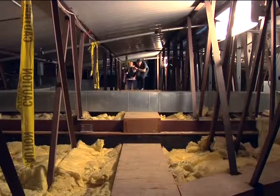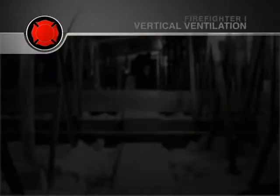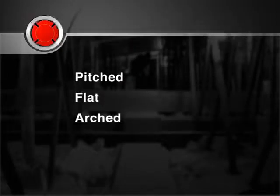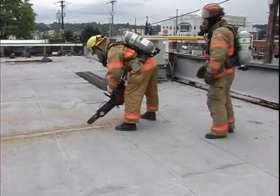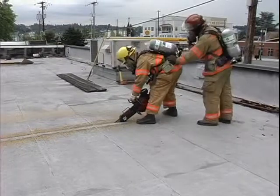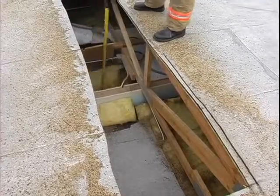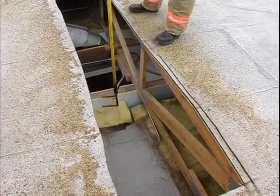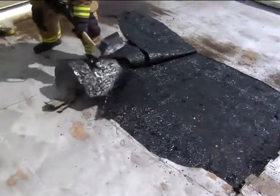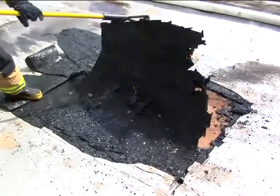Roofs can be made in a wide variety of shapes and with many roof materials and coverings, but the three main types of roofs are pitched, flat, and arched. Flat roofs are most commonly found on apartment, commercial, and industrial buildings. They may have a slight incline to allow rain and the elements to drain off. Flat roofs may be made of wooden, concrete, or metal joists covered with sheathing. The sheathing is then covered with a layer of waterproof material and insulating material. They are often mopped with asphalt roofing tar.